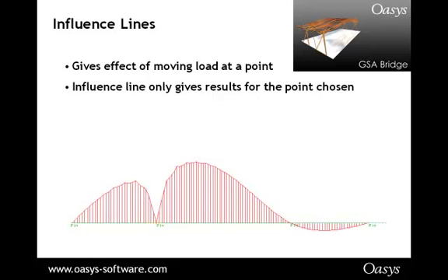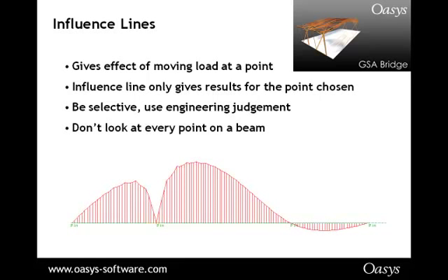Now they only give the results for the selected points, so you need to select these points and select sensible locations, which means don't look at every point, because you'll find with bridge loading there will be hundreds of load cases. And so you've got to try and cut these down to just the essentials.